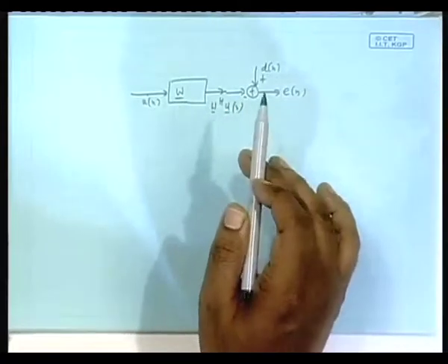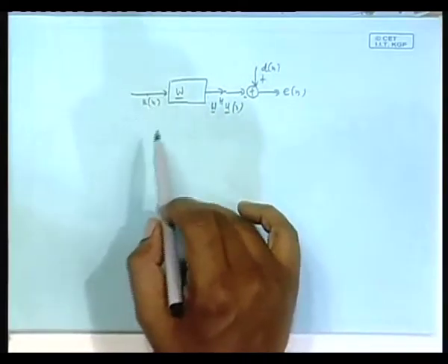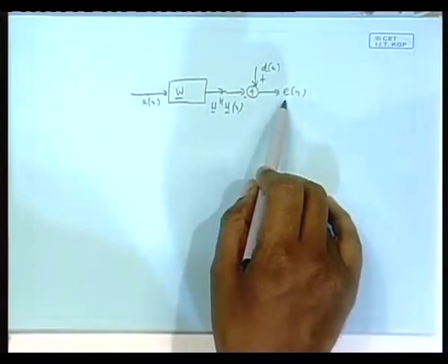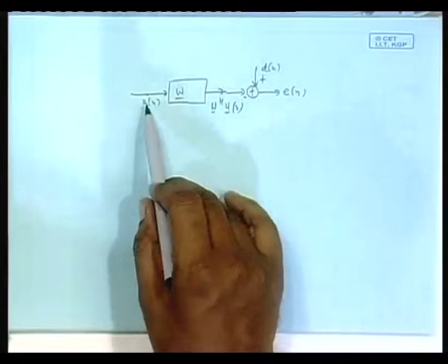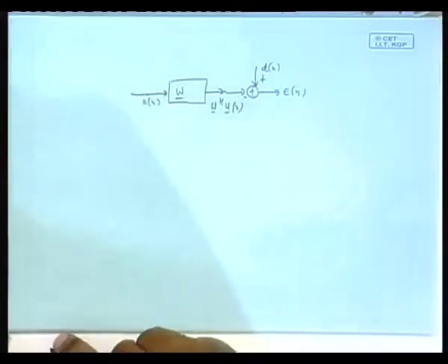That output I call a filter output, but basically it is nothing but linearly combining Un minus 1 up to Un minus P by some coefficients, so that the error norm square is minimized, and that error indeed will be orthogonal to each of Un minus 1 and so on, as we have seen from our vector space point of view.